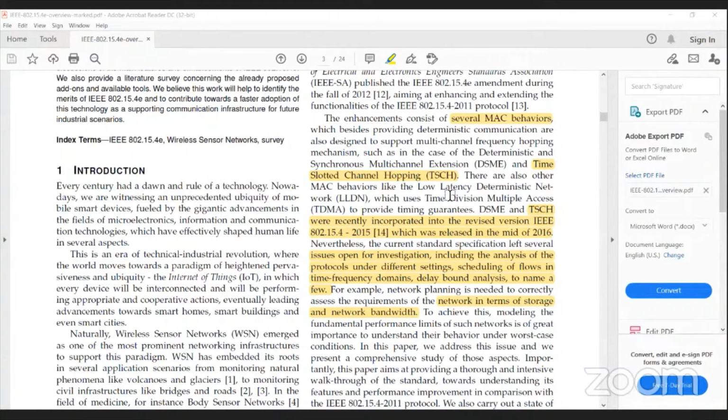And that is where you will have to differentiate between TSCH and LLDN. LLDN is something interesting. It says I'll give you low latency. Actually, it's like a knob. You can program what kind of low latency you need from your system. Yet if it is low latency, it need not mean deterministic, but LLDN combines both. It says I'm not only low latency, I'm also deterministic.